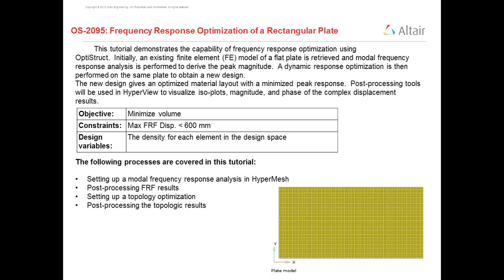The process which we are going to cover in this tutorial are setting up a modal frequency response analysis in HyperMesh, post-process FRF results, set up topology optimization and post-process the topology results.